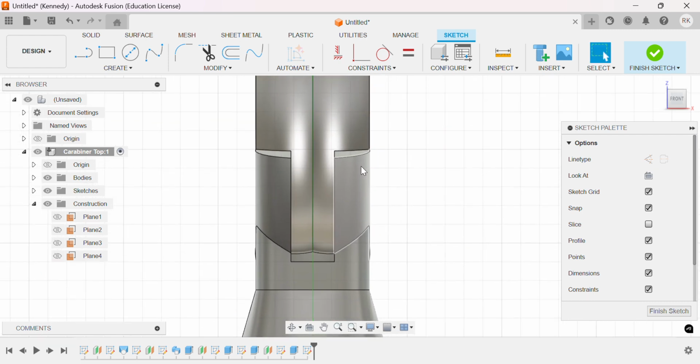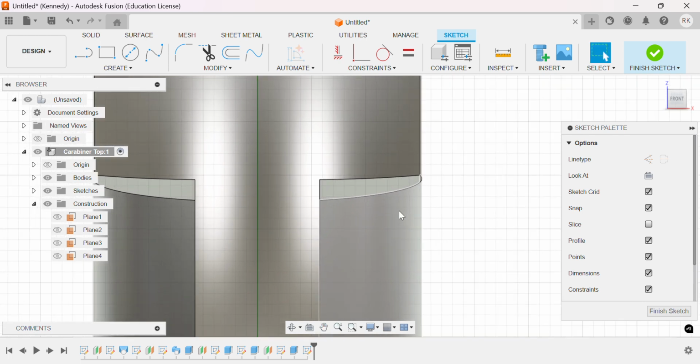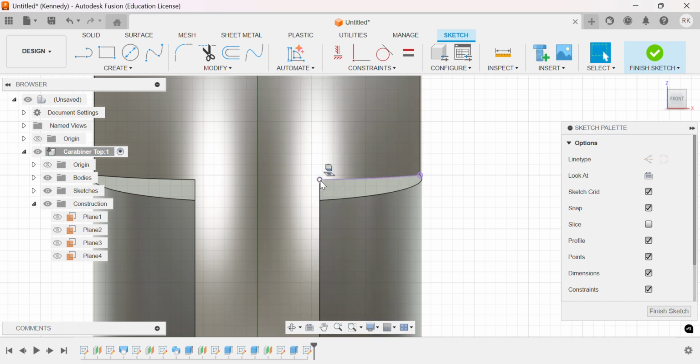Okay, so now this one's a little different in the fact that it doesn't quite work the way he often shows it in the video, so I'm going to manipulate this the best that we can. All right, so now what you're going to notice is if I put my cursor back here, I can select that line. I can bring up a white dot right there and right here. However, if I go up to my line tool and I attempt to place them on those spots, I cannot interact with them in any way, shape, or form. It's not going to do for me what I want it to do. So instead, what I have to do is go to the P key again, and I need to project that line, because the only point that we really want is this one right here.